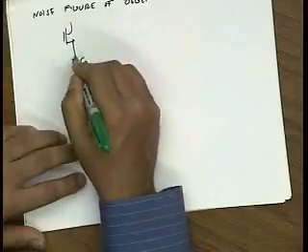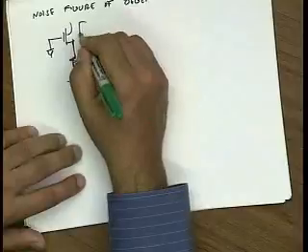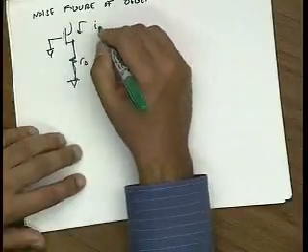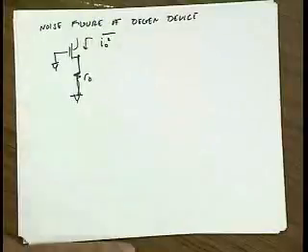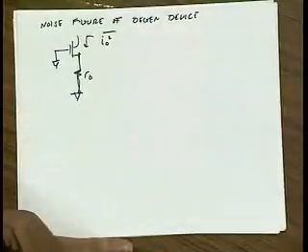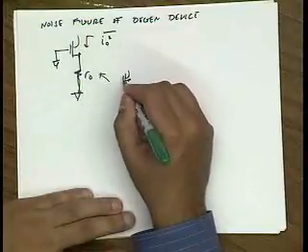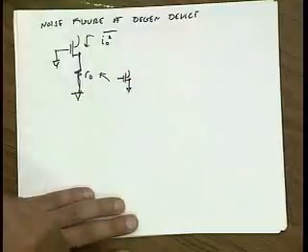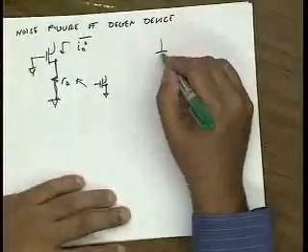So this is RO, and I'd like to find basically the output noise of this device. Okay, and this calculation is very similar to what we just did for inductive degeneration. Now this is basically our transistor in saturation. So let me draw the equivalent circuit here.